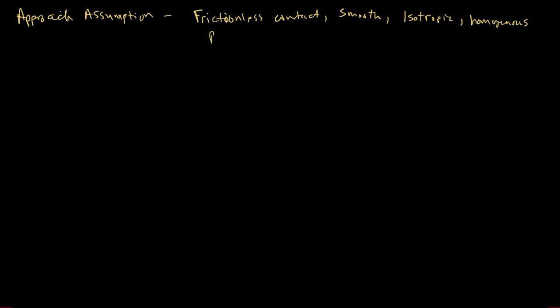And we are assuming that both R1 and R2, the contact radiuses of both the balls and the cylinders, are much greater than A in the case of spheres, or B in the case of cylinders, or we could just say they're much greater than A or B. Turns out that this approach is useful and gives us reasonable numbers for the max pressure, and so we use it.